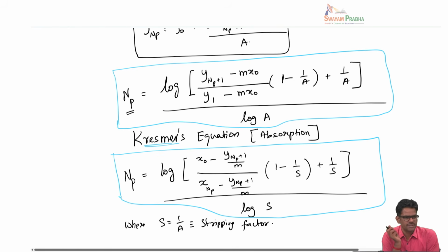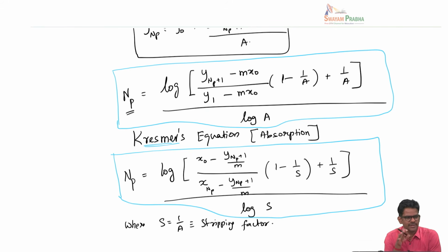So this Kremser equation is very important because if you look at GATE questions on absorption at a tray column, pretty much entire questions actually come in this application of this equation, because it's an analytical result. Very rarely you get graphical questions, and it's not that you have to memorize this. Generally these equations are actually given. You have to know how to use this equation, that's all. Sometimes this absorption factor A may not be given, that's something you have to calculate. Otherwise pretty much it's more like a substitution and